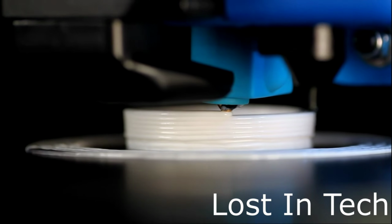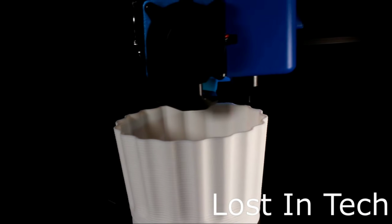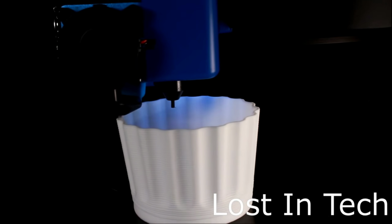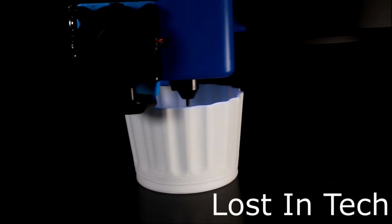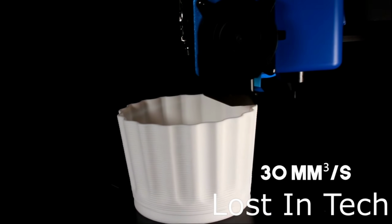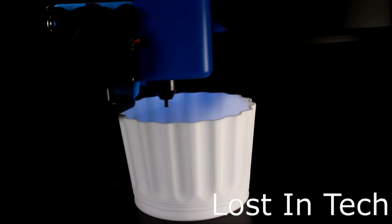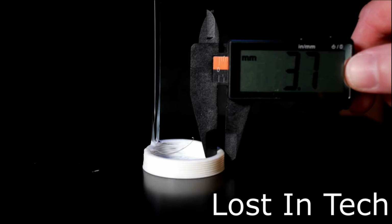There are several benefits to spiral vase printing. Firstly, the nozzle of the printer never has to break contact with the part since it is able to spiral continuously, layer after layer. This means that the surface finish of the part comes out really good. When the printer has to lift away from the part, a small amount of smearing occurs. Small strands will also form as the nozzle pulls away.